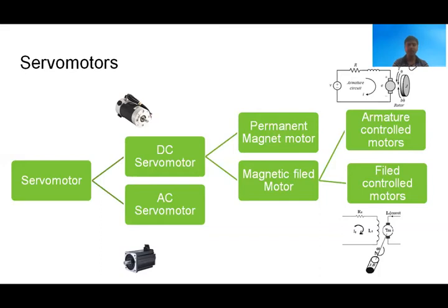It should also have steady state stability and a wide range of speed control. Then mechanical characteristics must be linear throughout the speed control range. Also low mechanical and electrical inertia, then it's very smooth to control the position of the object. And also the servo motor should respond fast. These are the important features of servo motor to select a specific servo motor for a particular application.